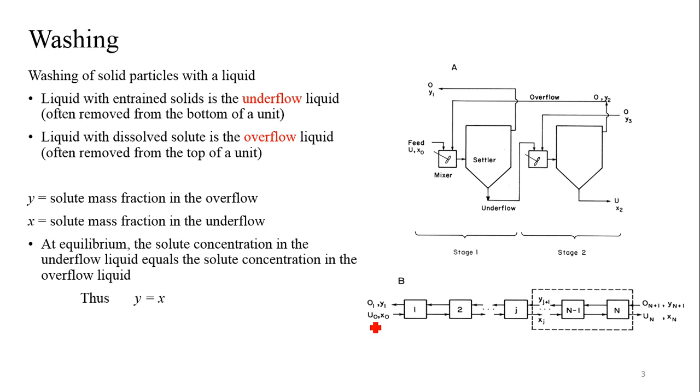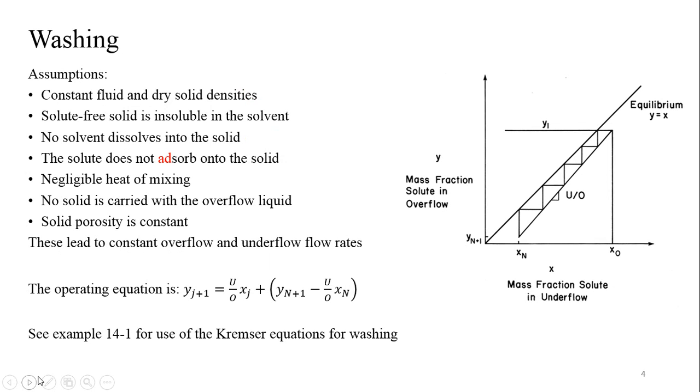Right? So we use X with the underflow, Y with the overflow. You see here a countercurrent operation. This one's showing various stages. All right. So a lot of what we've learned is going to apply here. So we can make some pretty direct analogies to what we've done previously with absorption and stripping and so on. And carrying it further, really looking at liquid-liquid extractions.